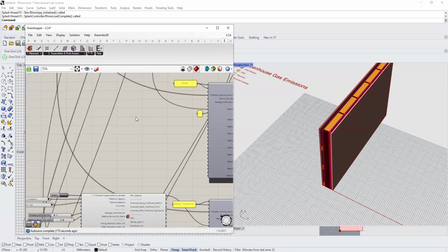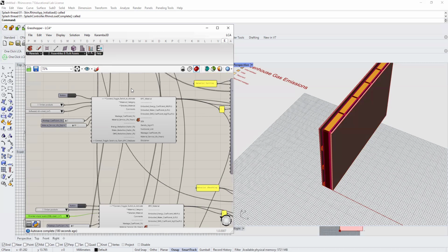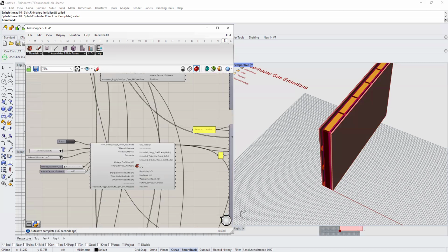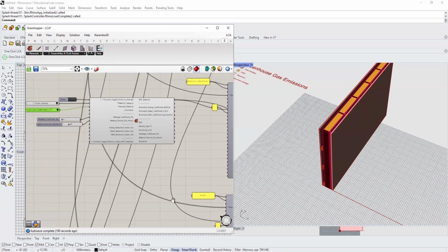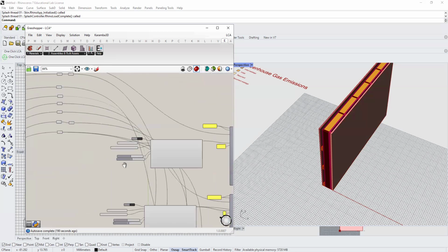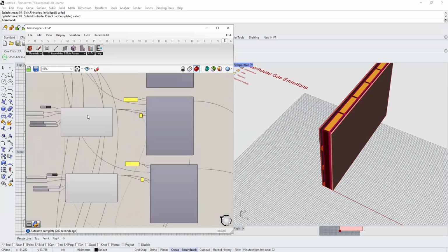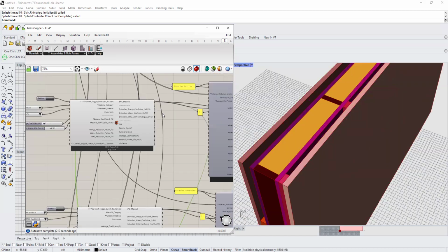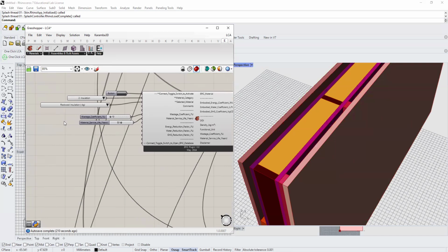And also for the studs, I used the same material that I defined for the fairing, the studs for the fairing. So somewhere I had the studs. They are just coming from this geometry, and here the material that I use for exterior fairing, I'm using the same material, but of course with different dimensions to define the studs. And then for thermal insulation, I went to the category of insulation, picked rock wool insulation.